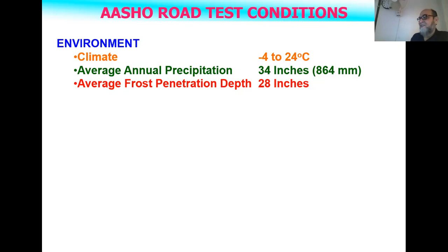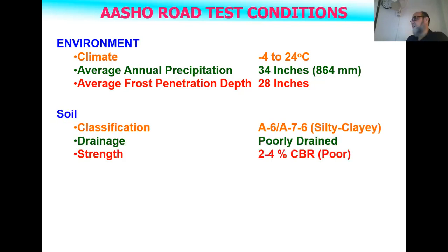In Karachi, most of the pavement design is based on the AASHO method. The main arterials, I mean. We don't design local roads. We design on the thumb rule. There is no valid method. There are templates, and that is applied without any thinking. So for major arterials nowadays, expressways, motorways, we design with the AASHO method. With all the discussion we had a little while ago, this seems to be very different from what I'm presenting.